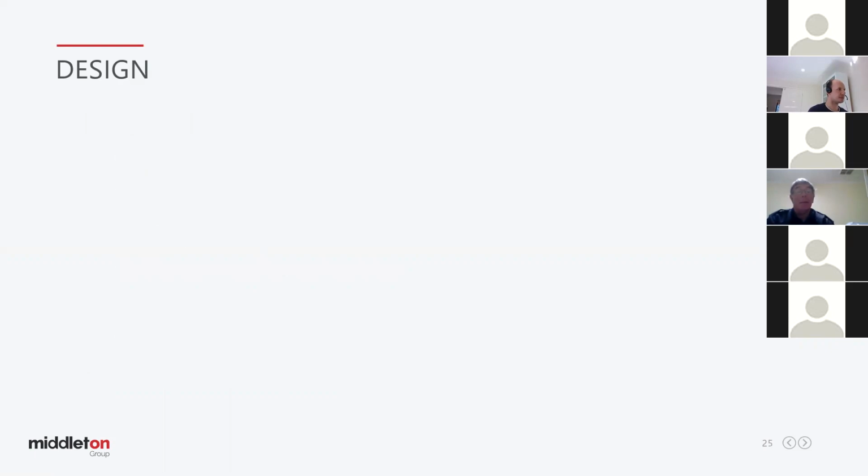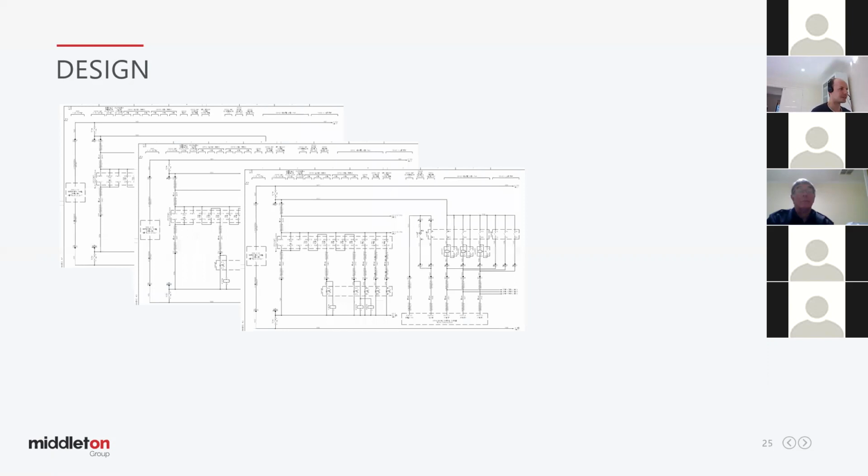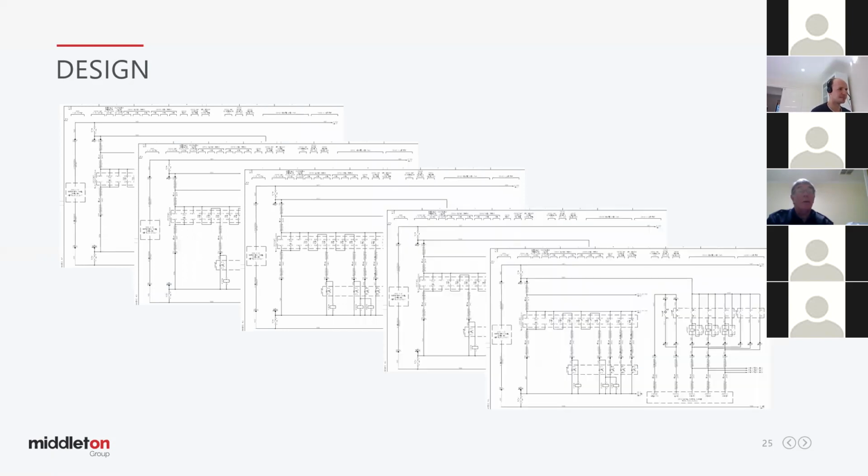So I kind of flashed through some of those items. But if you looked at it from a schematic point of view, this is what we'd be doing. This is very typical for a secondary design. You just keep pumping out schematics, and the schematics can take very different forms. A lot of secondary can be translated to a bit of an adventure, if I can call it like that. You need to do a lot of detective work. If you're tracing an old signal, which might not be referenced on one drawing, which may be shown somewhere else, there's generally another drawing at that site somewhere that shows the information you need. And your job is to try and find it.